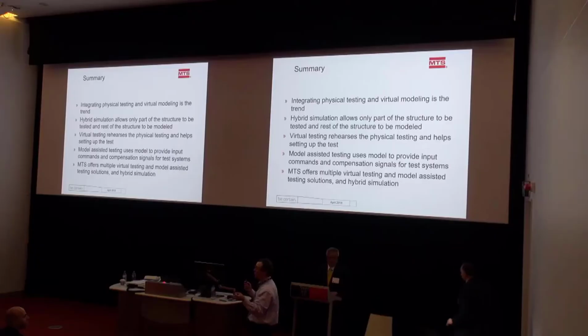So the damper property always changes, and to do an accurate test, you have to implement that hardware, the computer inside the vehicle. You cannot do the simple block cycle, because the computer is not there, and you are testing the wrong conditions.